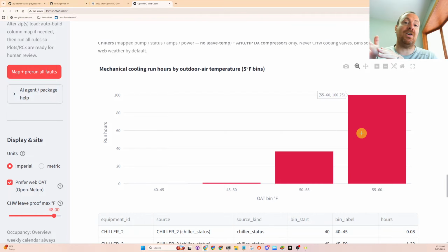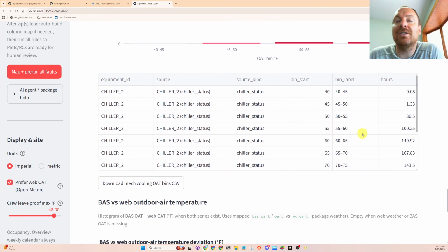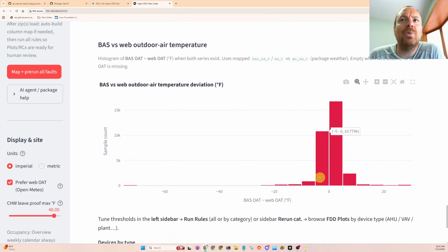Sometimes they have in-house carpenters that just modify the rooms and then they don't modify any of the ductwork or any of the sizing of the HVAC. Happens all the time. And then pretty soon you have to change the whole variable volume air handling unit to just serve this one room, which could be causing a whole bunch of problems.